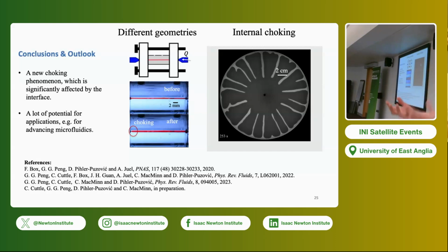I can tell you that experimentally, in the first version of the experiment, what happens in practice is there is a massive spike in the pressure, and our syringe pumps cannot overcome it, so they just stall, and therefore you are in that position where you're touching the opposite wall, and you stay there, because you're not pumping anything in anymore.